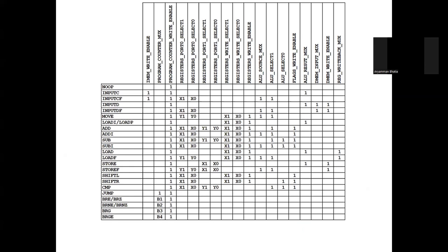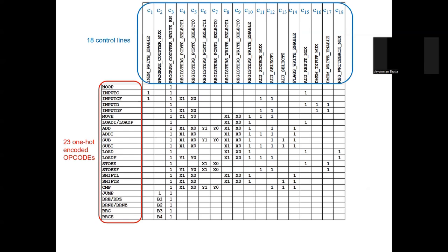So that is how the combinational logic works, right? And we can easily achieve that by just setting whatever values we need and ANDing them with the line that comes from the opcode detector, because we only want it to be executed when that particular line is 1, right?